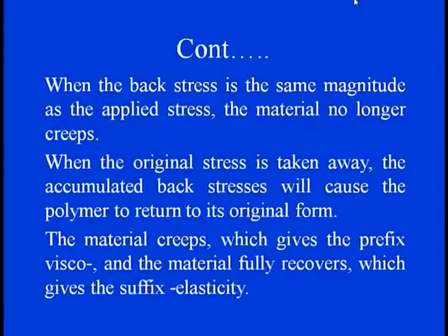When the back stress continuously increases and reaches the same magnitude as the applied stress, the material no longer creeps, and when the original stress is taken away, the accumulated back stress will cause the polymer to return to its original form.